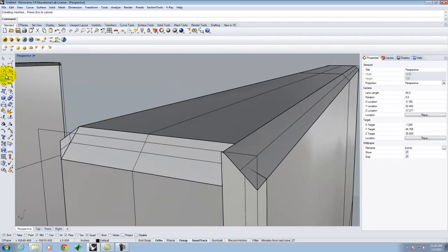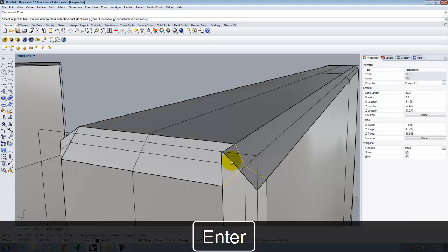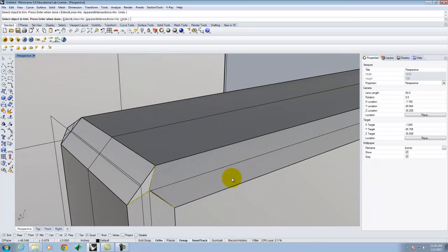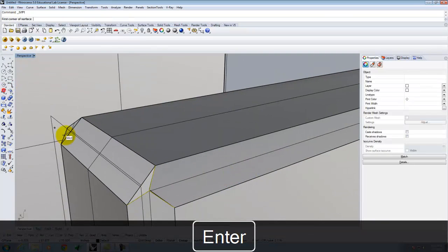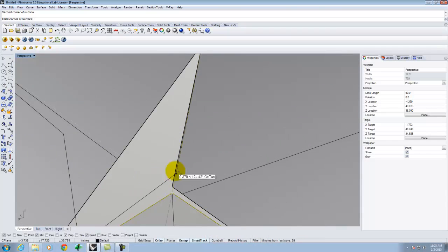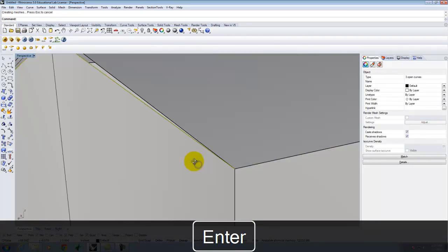So I'll repeat that again. This time I'm going from the center out to each spoke here. There it is. We go ahead and select it. And I'll use trim. Trim that off. Alright, looks pretty good. Hit enter. And I'll use a surface from 3 or 4 corner points. 1, 2, and 3. Okay, looks like something happened on this surface there.